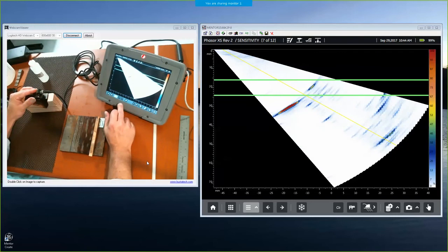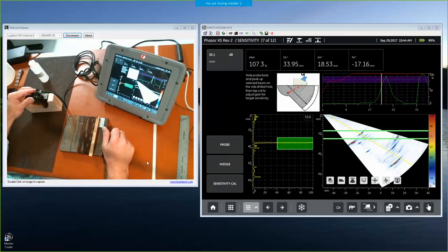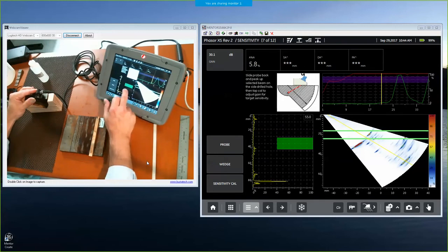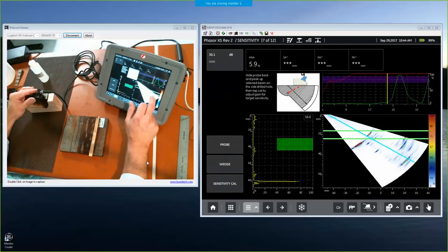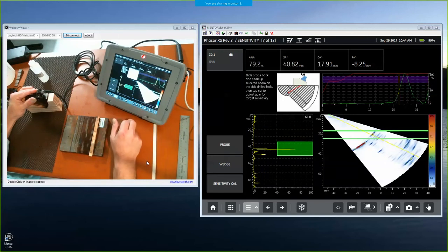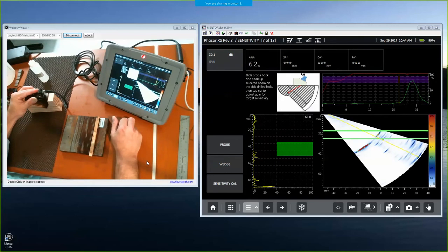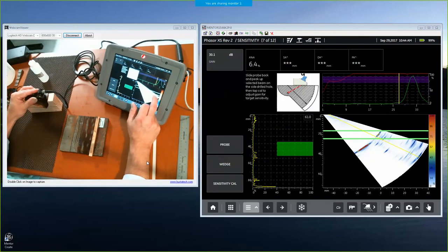So if you go to your A scan right there, when you go to those different angles, are you still getting 80% even off the selected beam that you're at? Well, as I move, the A scan is always going to reflect whatever the selected beam is. Right, here you're not at 80%. So as I walk the indication to a different beam, of course I lose it on that A scan.